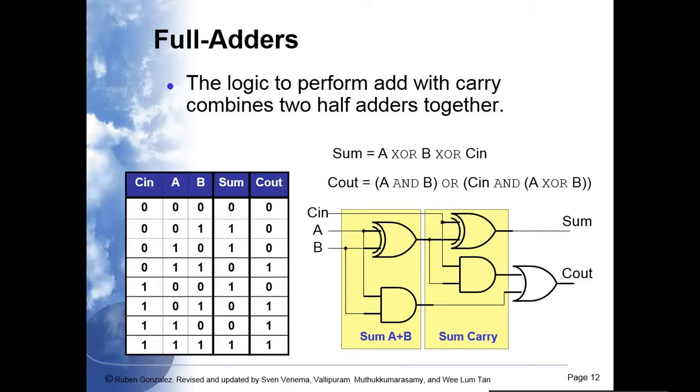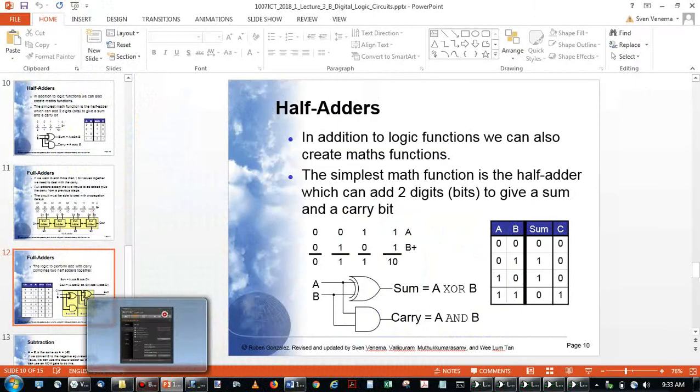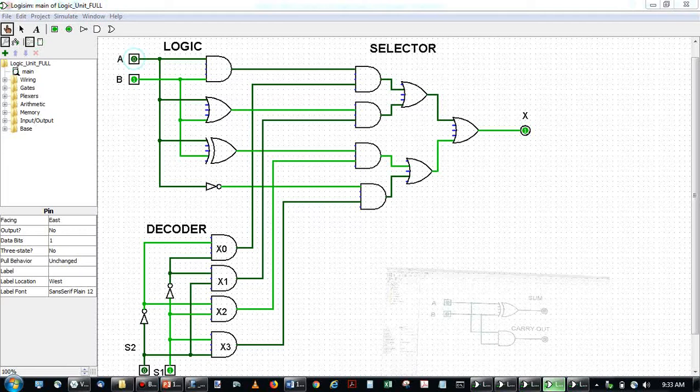And then there's an extra OR gate. What did we say OR gates do for us? They combine things. AND gates block things, OR gates combine things. How many carries do we have with our two half adders? There are two carry outs, right? So we need to combine them somehow. So if you get a carry from somewhere, it should propagate. It should go through and come out on the other end. That's basically what that's saying. So let's just have a look at the logic for that.